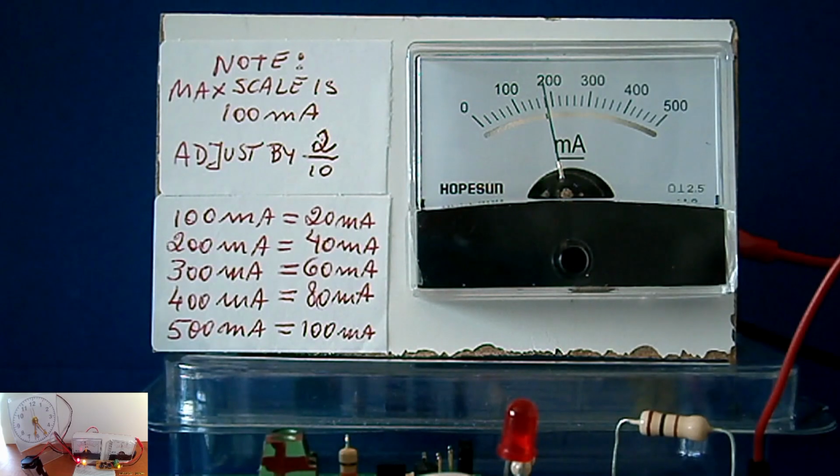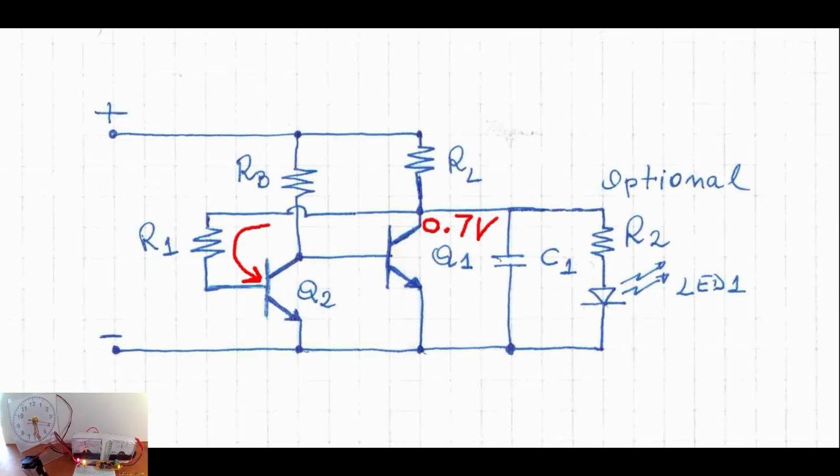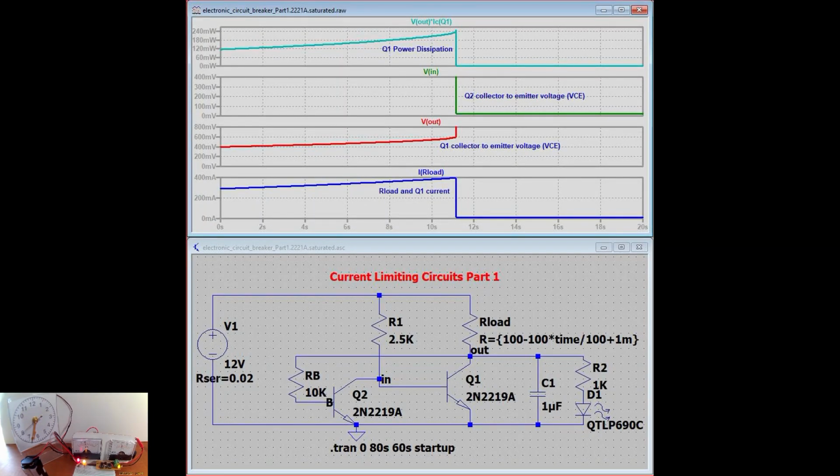They all followed two objectives. 1. Limiting the current by shutting down the circuit when the pass transistor, BJT or MOSFET, collector to emitter voltage, VCE, or drain to source voltage, VDS, reaches a voltage drop around 0.7 volts. 2. Avoid the use of heatsink devices.